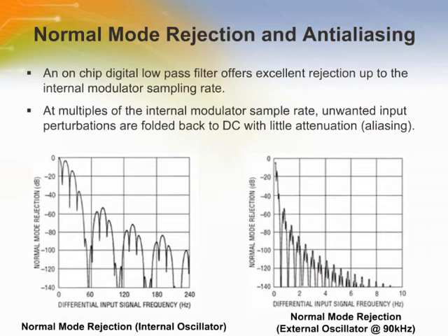The value of oversample ratio and the sample rate Fs determine the filter characteristics of the device. Since the oversample ratio is typically large, greater than or equal to 64, the digital filter offers excellent rejection of input noise sources and simple anti-aliasing requirements.